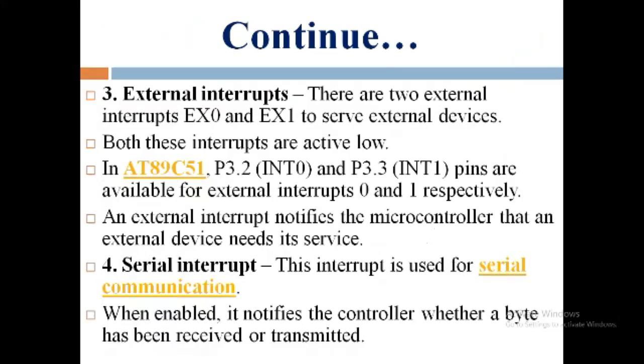Then the third interrupt is the external interrupt. There are two external interrupts, INT0 and INT1, to serve external devices. Both these interrupts are active low. In 8051, P3.2 INT0 and P3.3 INT1 pins are available for external interrupts 0 and 1 respectively. An external interrupt notifies the microcontroller that an external device needs its service.